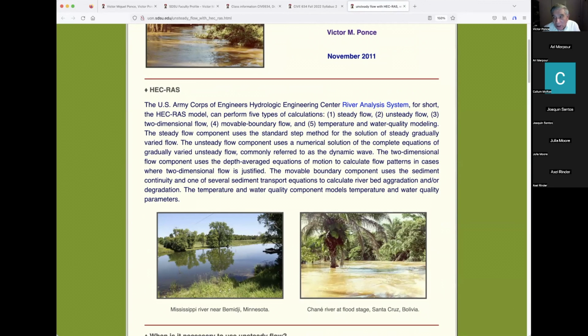Well, first of all, it used to be HEC-2. From 1968 to 1998, for 30 years, it was the character cell model of the Army Corps for hydraulics. HEC-1 was hydrology, HEC-2 was hydraulics. In 1998, the Corps created their GUI versions. And so HEC-2 was going to be converted to HEC-RAS and HEC-1 to HMS. The difference is that HEC-2 only did one part, the steady flow, while RAS does 6 parts, and it keeps adding. So RAS is a much fatter model than HEC-2 ever was.